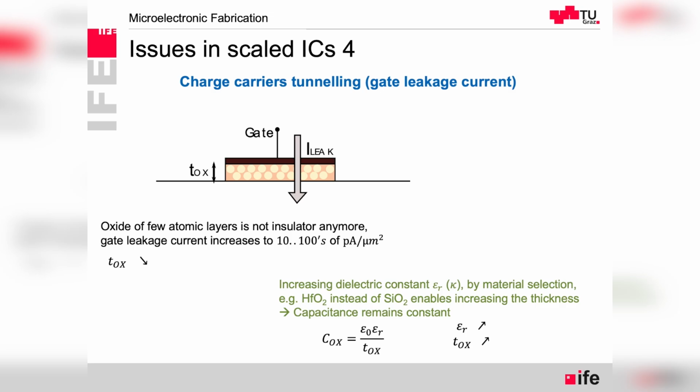So high dielectric constant means that we can make thicker transistor and still having the same oxide capacitance. And then the leakage current with the thicker gate oxide, we have more atomic layers, and with the good quality oxide, the leakage current is much improved, is much lower.